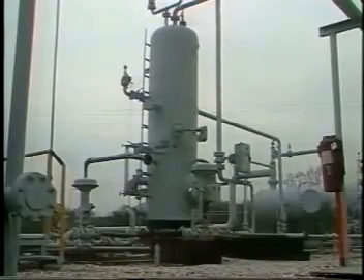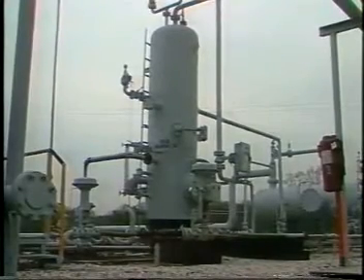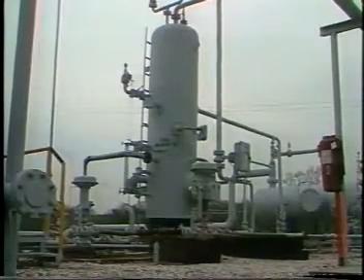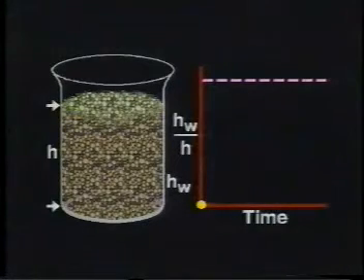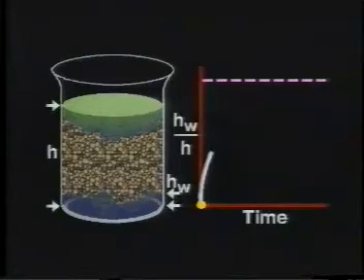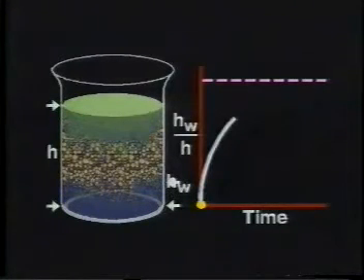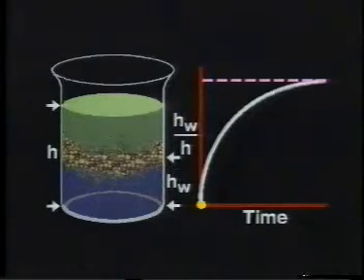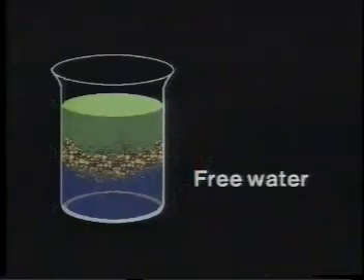We shall look next at the differences between two-phase and three-phase separators, before discussing the design considerations of separators in general. When oil and water are mixed with some intensity and then allowed to settle, a layer of relatively clean water will appear at the bottom. The growth of this water layer with time will follow a curve as shown here. After a period of time ranging anywhere from 3 minutes to 20 minutes, the change in the water height will be negligible. The water fraction obtained from gravity settling is called free water.